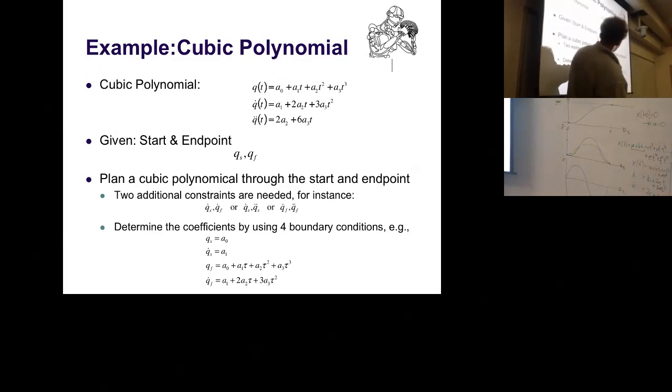We do the same thing for the final position. You need the movement time, tau. Plug this in. You already know A0 and A1. And then you have to solve for A2 and A3 based on your final position, and you have another equation for the final velocity where A2 and A3 appear. So you have 2 equations with 2 linear unknowns, and we agree that we can solve that. That's essentially what comes out here. Well, you have to solve that, so sorry. I haven't done this, but it's kind of okay, I believe.